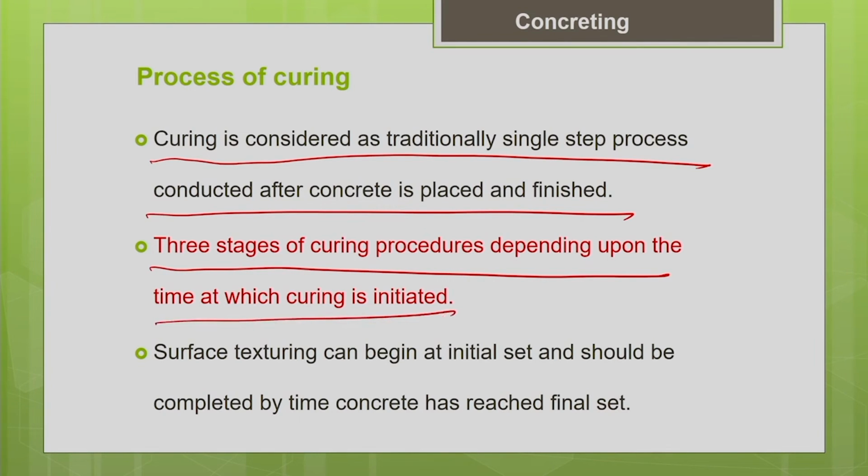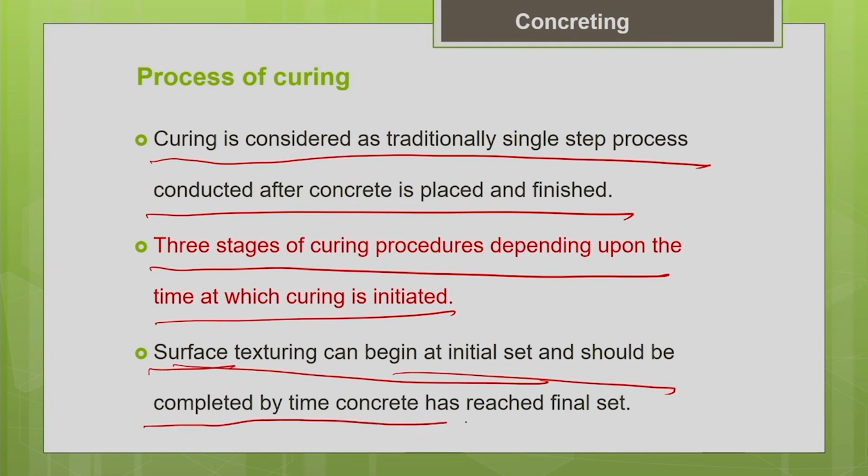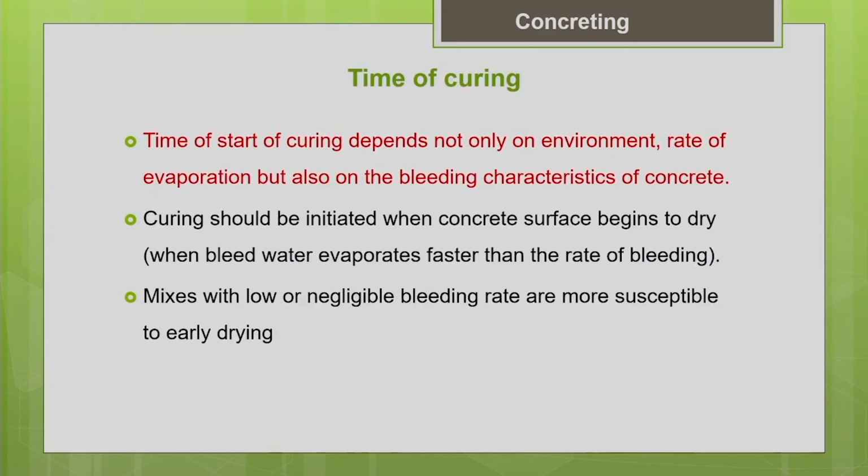So, as we discussed earlier, for finishing we work between the initial setting and the final setting. Surface texturing or finishing can begin at the initial set and should be completed by the time the concrete has reached the final set. Now, we will see what time we should start the curing.